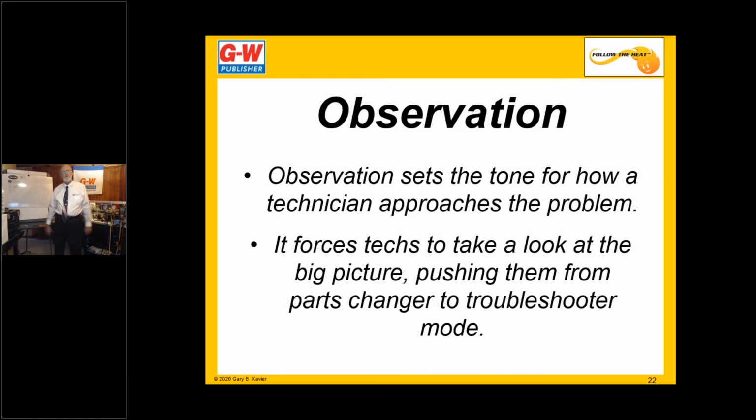That was not observation. I was trying to be a parts changer. I was going to dive right into that pump because it wasn't running. Had I stood back and observed for a moment, thought logically through the problem, logic would have told me, check the power source before you start to take the housing off the pump. And I didn't do that. So we can all learn, but we have to observe.